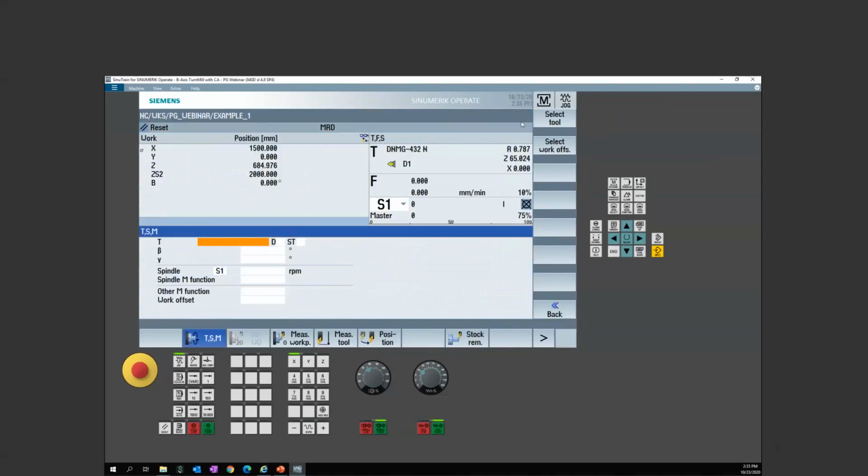Now, I don't happen to have a swivel carrier running right now. That would probably be because it was canceled maybe through a part program, so you don't have to worry about that. Normally if you're a mill guy, you're looking for the swivel button that doesn't exist on the lathes, because all you have to do is just give it a command, and it can be a redundant command like a B0, and that'll turn on my carrier. So now I always want to make sure that this carrier is running, because this is what tells me it's tracking that offset.